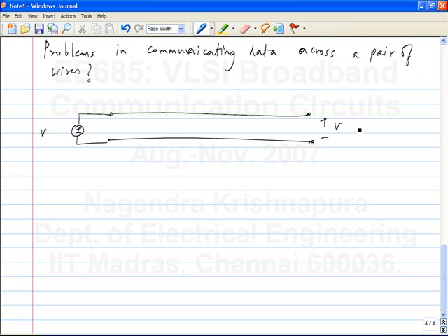So why do we even have a course about the whole thing? Okay, parasitic capacitances. So what happens? Where is the parasitic capacitance now? In this situation. So this is the kind of scenario that we are discussing, right? Every scenario that I outlined before, whether it's Ethernet or connections on a chip, is something similar to this. You have two wires and you have to transmit data across it. So this serves as a good model for everything that we saw before. Now, what is the problem with this? Why do we have to even think about transmitting data, right? You apply voltage on one side and it should appear on the other side.